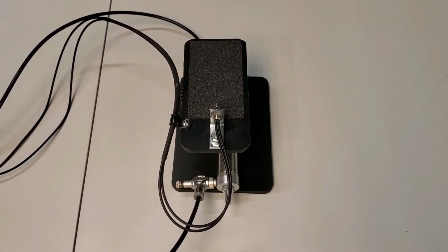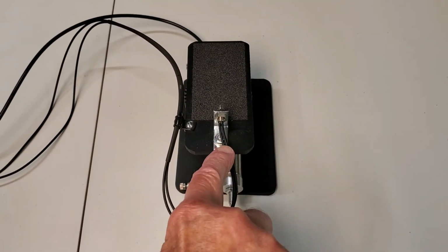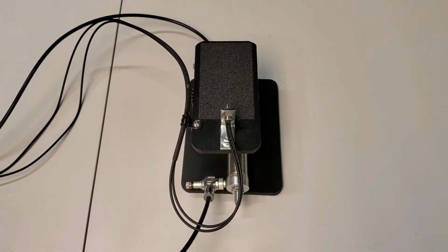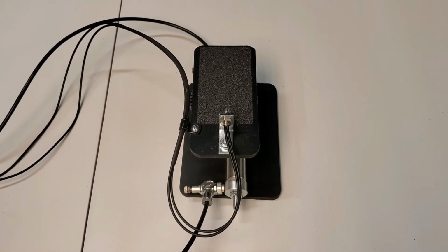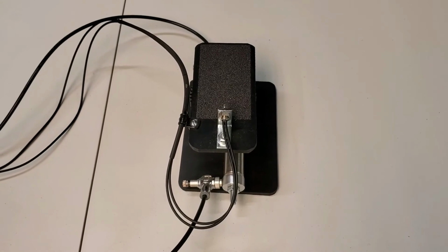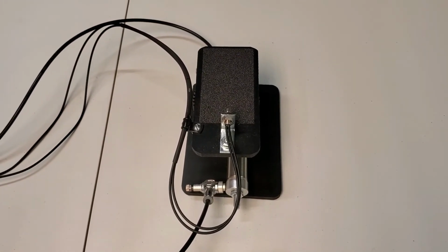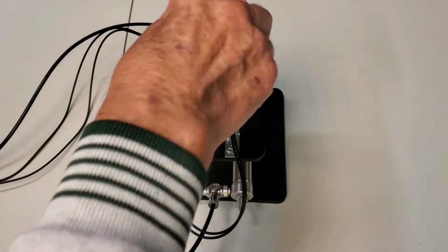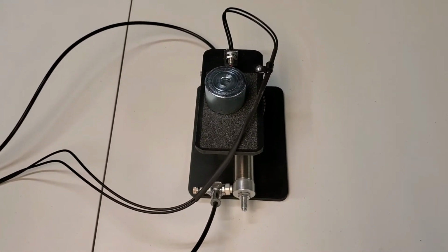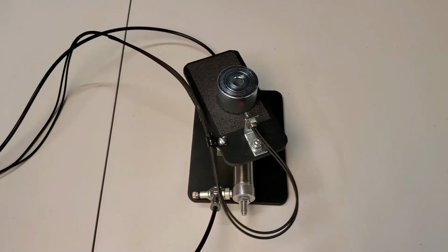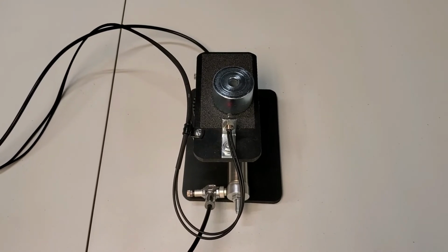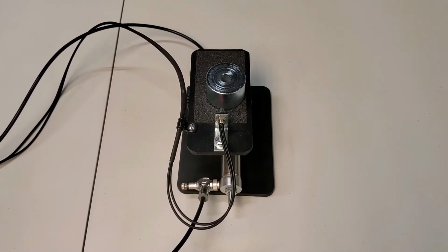A typical application for a reflective fiber optic sensor is that of part recognition. In this particular case, this is attached to a rotary actuator. So when it sees the part, it's going to rotate, and it's going to hold it in a specific position for a given time, and then it's going to return. So the sensor itself is saying, I see the part, I will turn it around, and then I'll return it when it's all done.